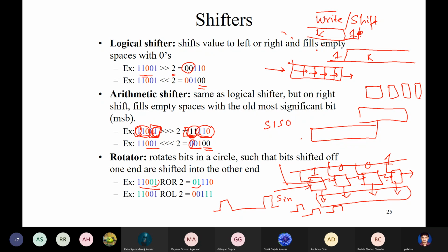If it is parallel in, parallel out, you kind of need a latch. So there are two situations possible. One is write, and then you latch it for one cycle, and then you read. And for serial in, serial out, this shift would always be on. You would serially shift in and shift out. I am not going into the logic for this write shift line. That would depend on what type of flip-flop you are using, but it's not very difficult to implement.